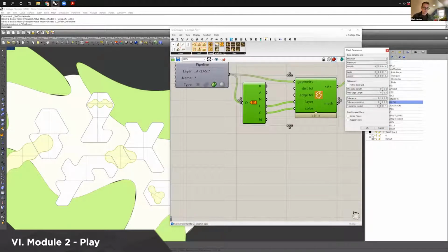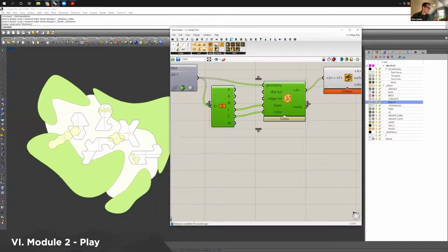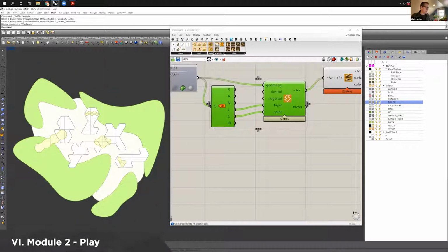We're usually working in feet at Landau, so I do 0.01, return, and then say okay, and you see that it makes those settings a little better. There's a similar thing in the Rhino settings as well, where you can change how detailed surfaces and things are being drawn. But one thing that's happening is all the colors are being blown out, right?